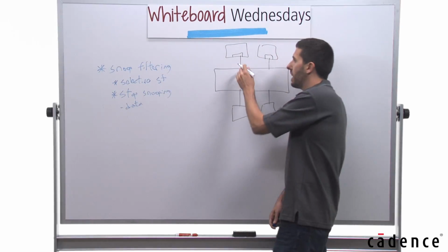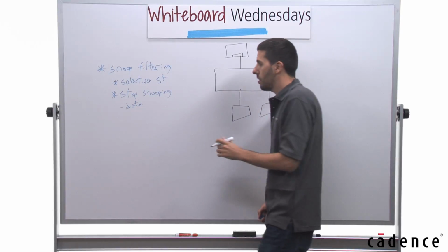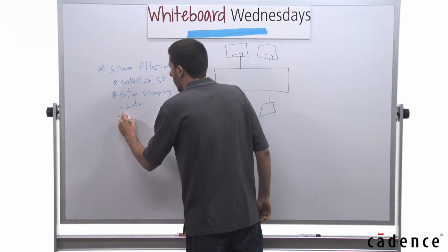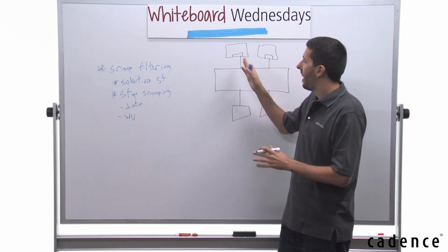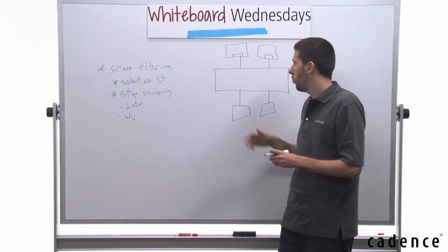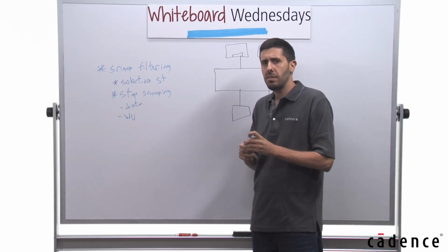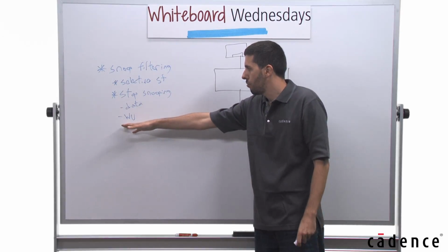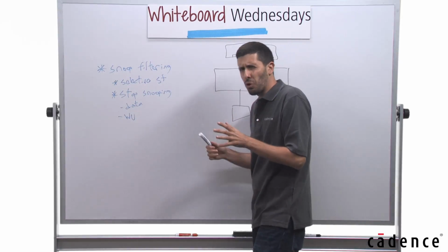For example, if we get data, then we stop snooping because we already got the data we want. Or if a master replies with was unique, meaning I had the line, I'm the only one with the line, don't worry, so we can stop snooping. We need a way to support all these different modes in order to make sure that we do the match correctly.